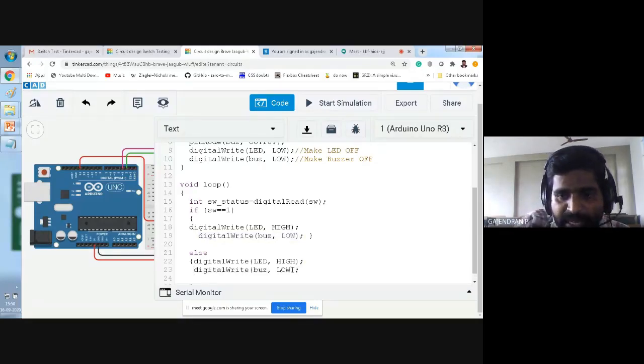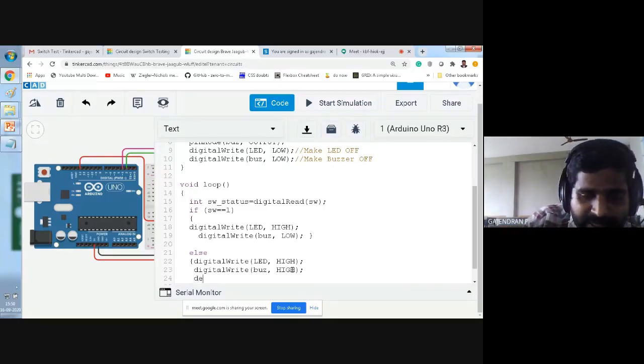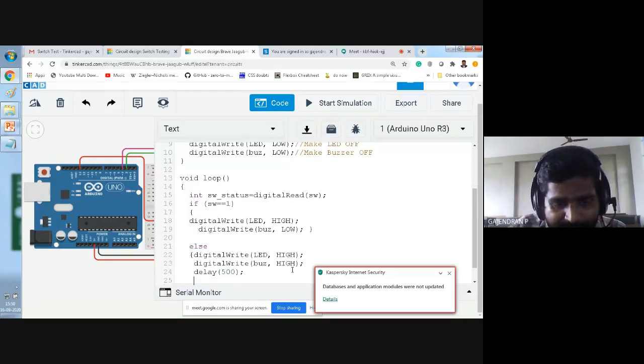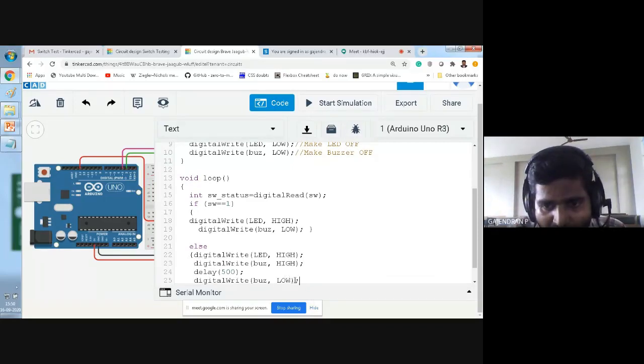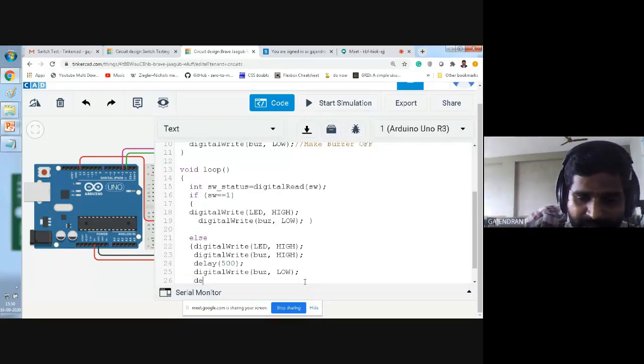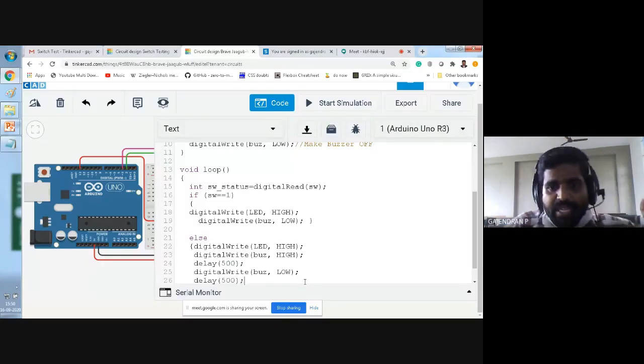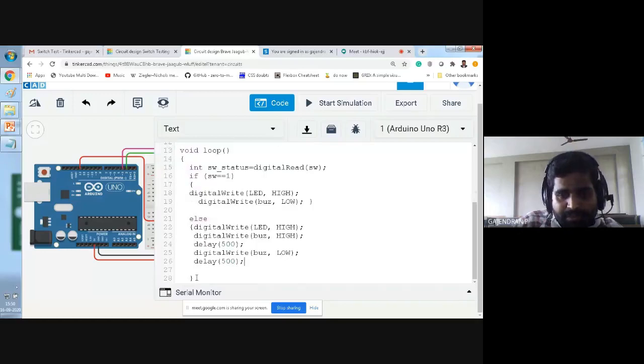Okay, buzzer high for some time. Let me give the delay as 500 millisecond. Okay, then low for 500 millisecond. Is it okay?